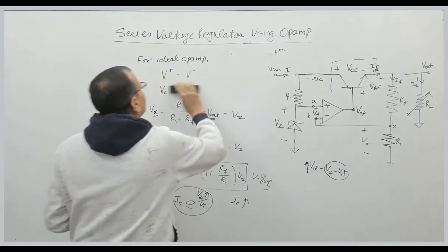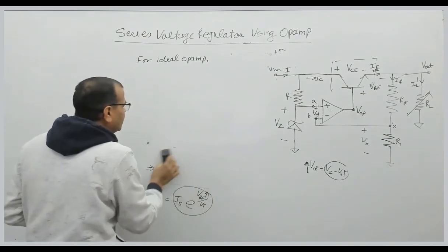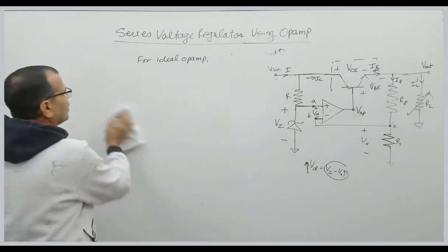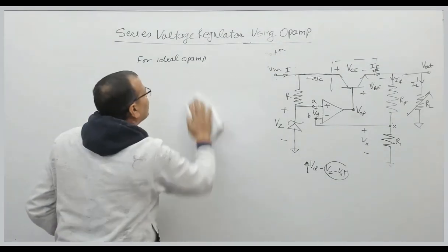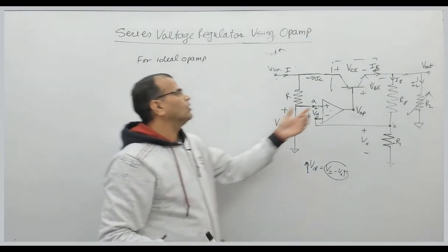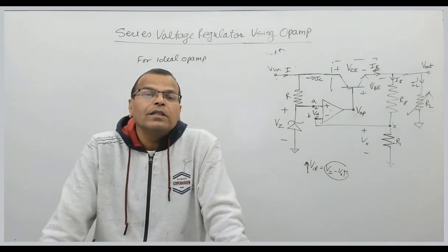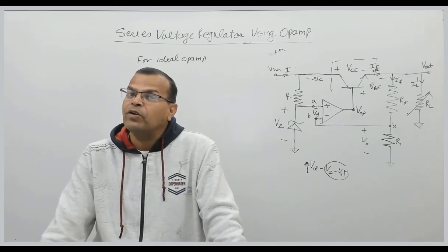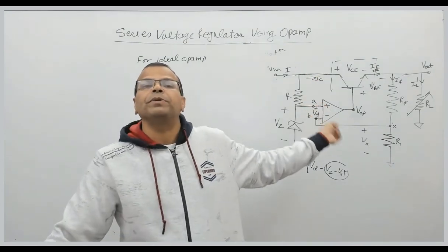What is power dissipation? The power dissipation is because of the BJT which is connected in series, and that is called series pass transistor. The full load current of the regulator will be passing through the BJT, and that results into the power dissipation in the regulator. So power dissipation of this regulator is because of this series connected BJT. And here BJT is used as an amplifier, and in amplifier collector junction is reverse biased, and because of reverse biased collector junction there will be heat dissipation at collector junction, which will be heat dissipation of this power supply.